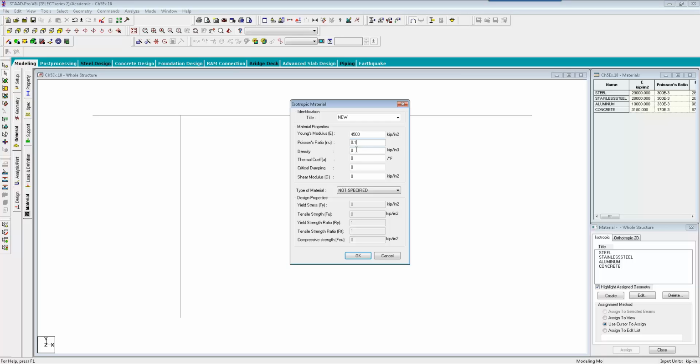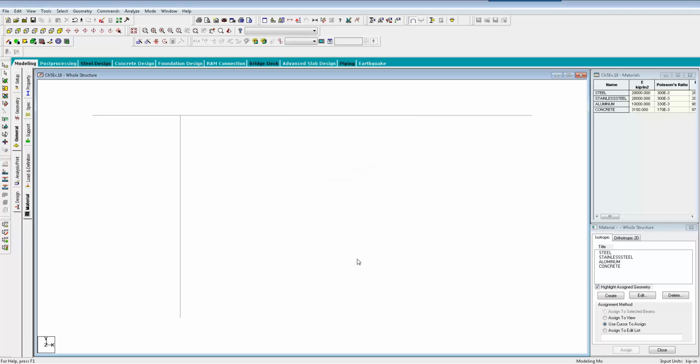and when my Poisson ratio is 0.1, based on the calculation, shear modulus is 2045.45 KSI. Then add, OK. So we define the material. The next step is that we have to define the cross section. So we have I and 2I.